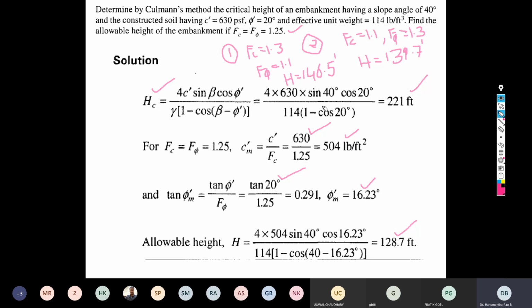Up to a certain height, the cohesion is dominating. For the remaining height, the friction is dominating. So it is not the solo mechanism of the cohesion or the solo mechanism of the friction. They proportionately change their role depending upon the height. You got it? But at what height does the friction dominate the cohesion, or the cohesion dominate?